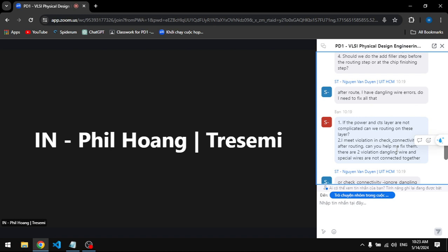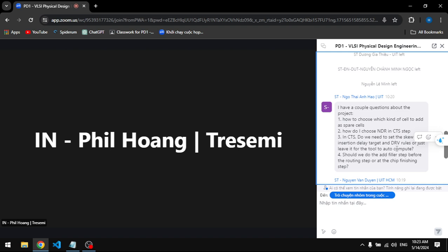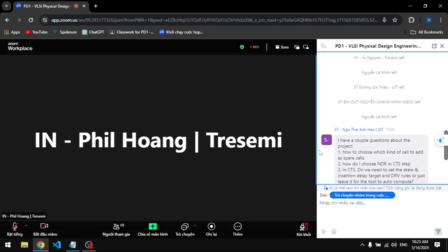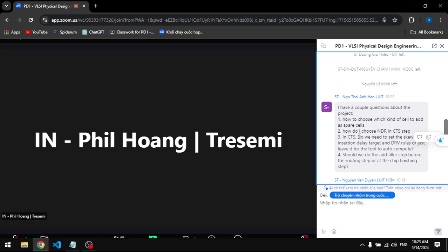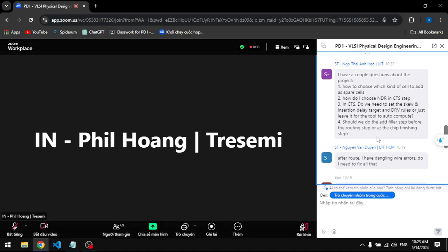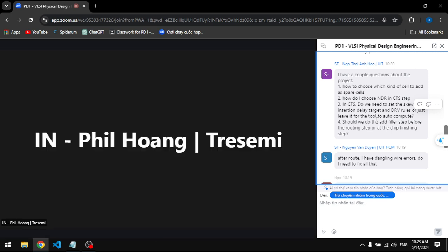It deals with resistance, right? Because of narrow width and electromigration, when you have clock nets switching all the time at very high frequency and very high power, you don't want the resistance to limit your rise and fall time.